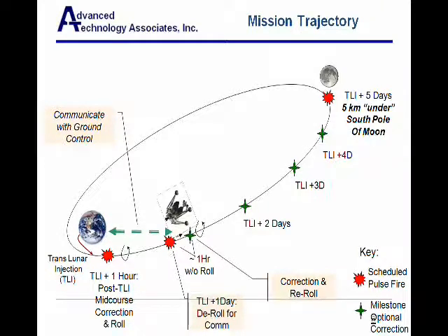We conducted limited trades on the communications that would be required for this mission and the thermal requirements inherent in this type of transfer. We incorporated the results of these trades to design a mission that used an optimum 5-day transfer time from Earth low orbit to the Moon. We analyzed the avionics systems using an error budget from a separate analysis. This provided us a sizing of the propellant requirements for mid-course corrections.